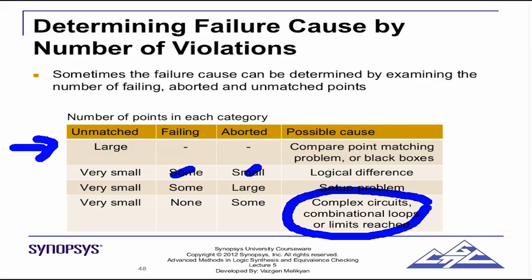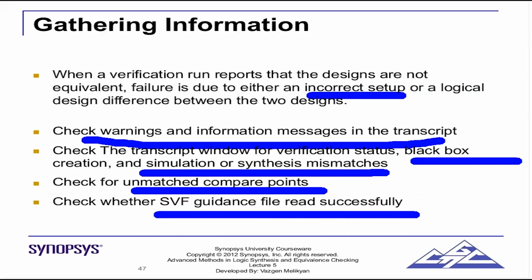Secondly, you might face these types of cases where there are setup issues, right? Usually, if the version of Design Compiler is stable and the Formality version is stable, and it is being used by different design groups in your team, then first debug the setup. First debug the variables, what you have set the variables to be. Debug that you have set it correctly for clock gating, and that you have read the SVF file correctly. So debug all such things first before going on to the logic cone itself.